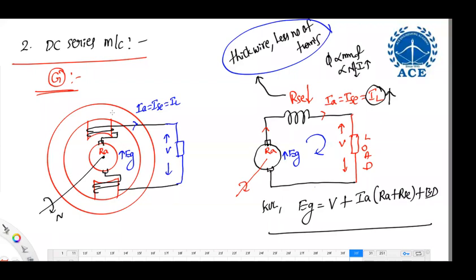Yes, sir. That's why. Sir, in the universal motor, we have two types, no, sir? One is AC and DC type. We can give AC, DC also we can give. That is universal. We can use both types, AC and DC. Sir, in our home, we are using a universal motor as an AC motor, no, sir? Where is the DC one used, sir? Whatever motor we have in mixers is a universal motor only. Generally we are giving AC to that. But if you have a DC battery, try to give it and check whether it will run or not.